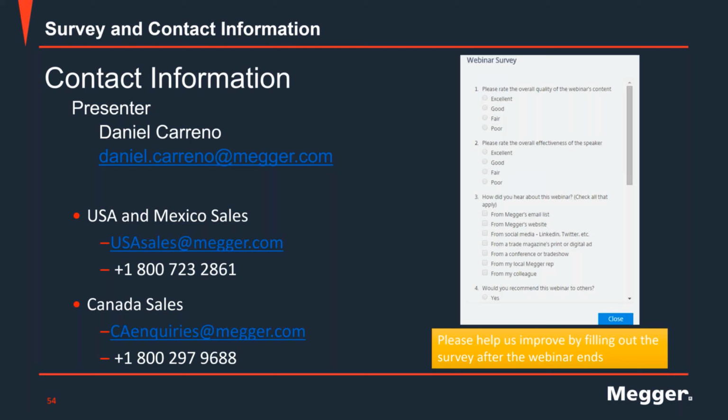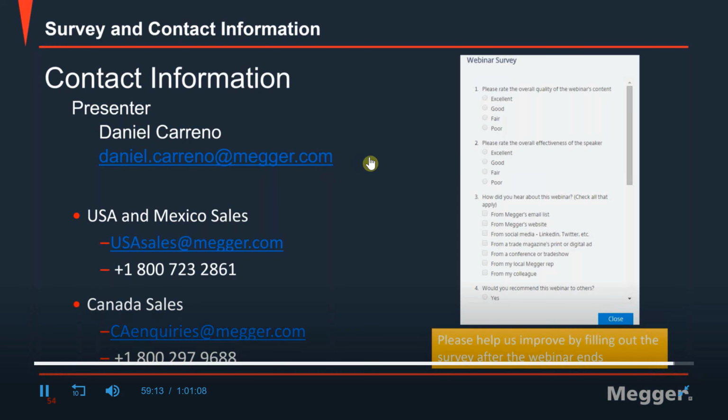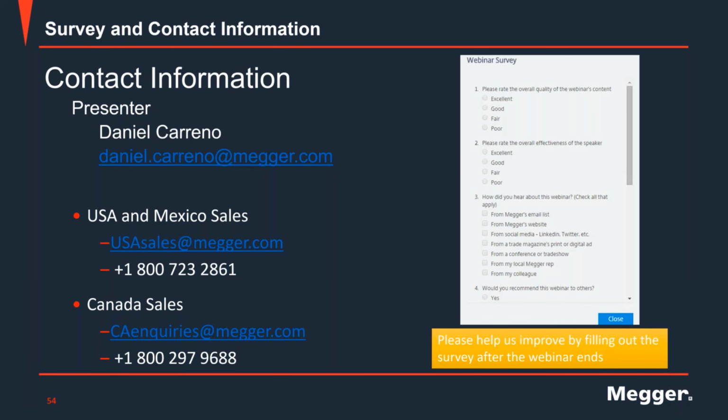So if the results are outside those limits, the first thing that you want to make sure is that it's not an operator error. Check your tap voltage. Check your tap position. If you're testing on a transformer with a tap changer, make sure that you're testing on the right tap position. Because if you're testing on a different tap position, then the nameplate voltage would be different than the measured values that you're getting, and that would result in a higher error.